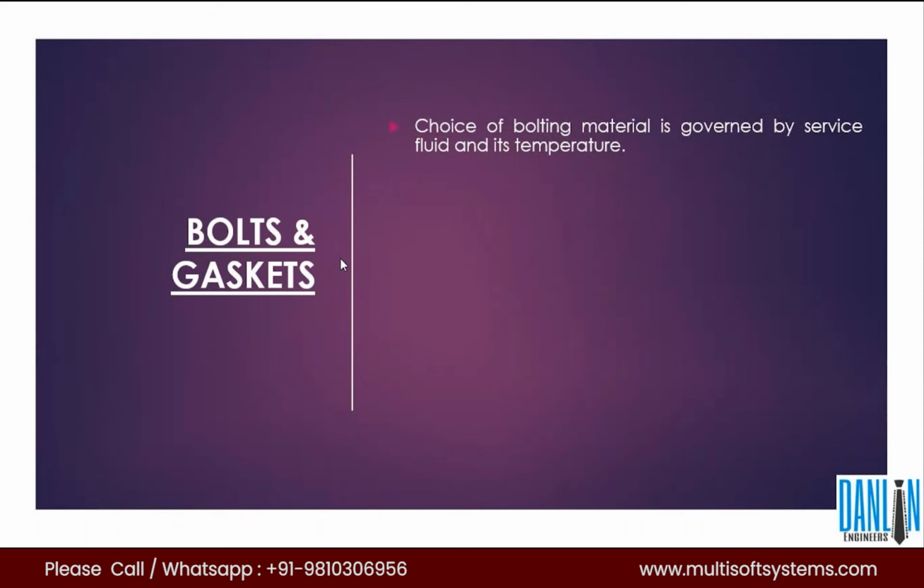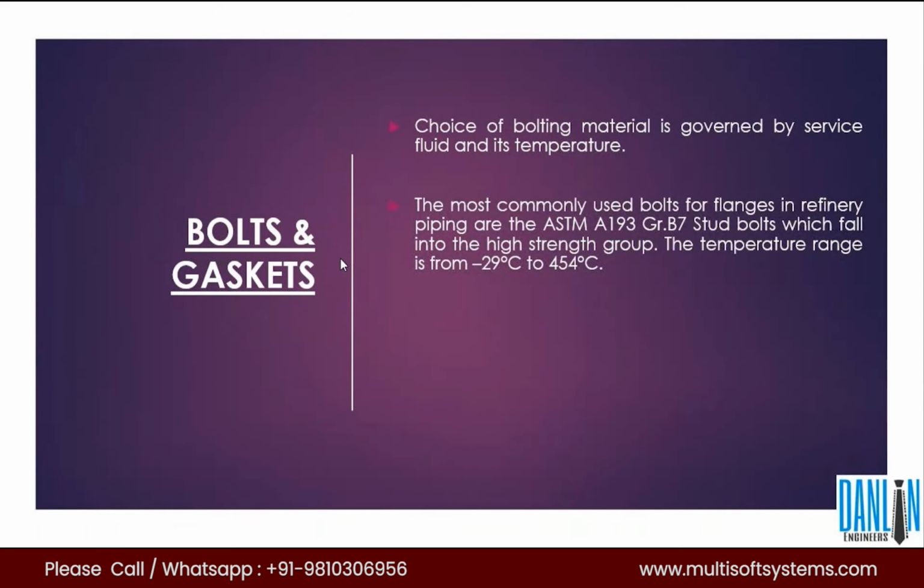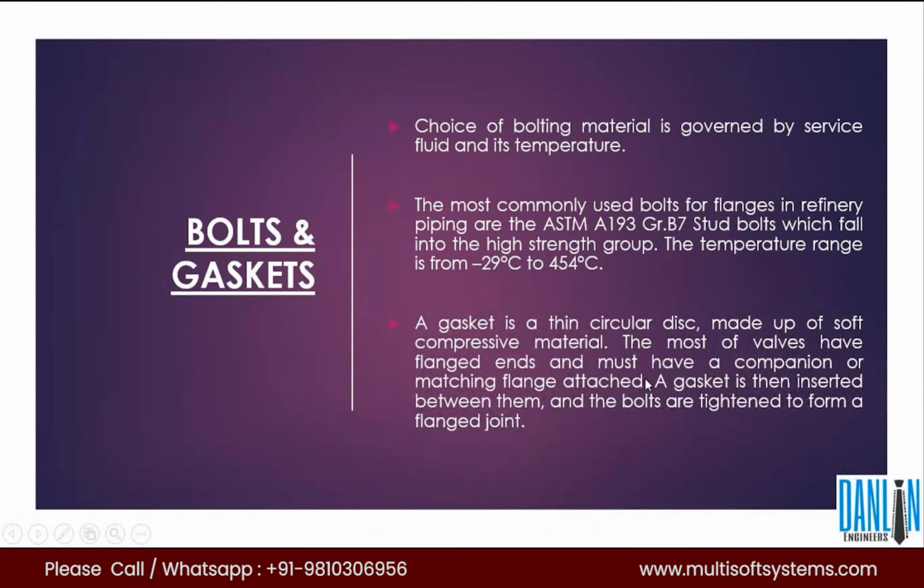As a stress engineer, he must know the bolt details and the gasket details. Most probably we use A193 material as the stud bolt at this temperature, and spiral wound gaskets, and many other gaskets.